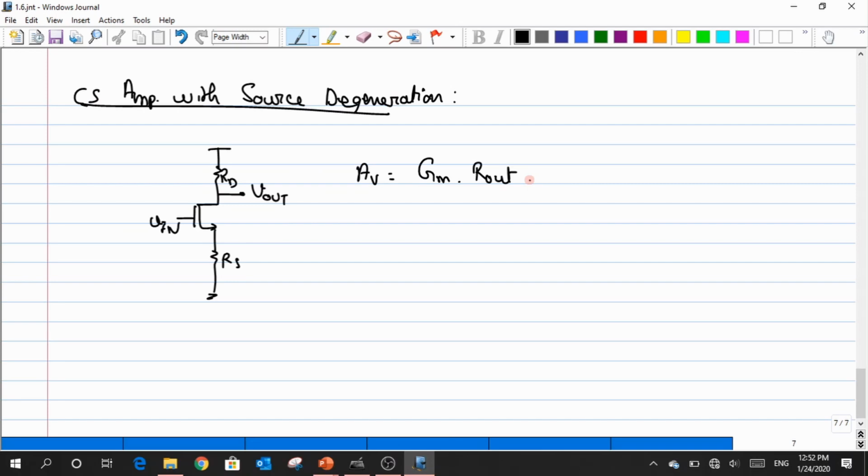I think we have already done this, right? I gave a hint, something like this. So it would be like minus gm1 into Ro1, and then at the bottom we could write as simple as Rx. Now what is Rx? It is nothing but the impedance that I see from the bottom, from the drain of my M1 transistor. What is that impedance? R naught. That's it.